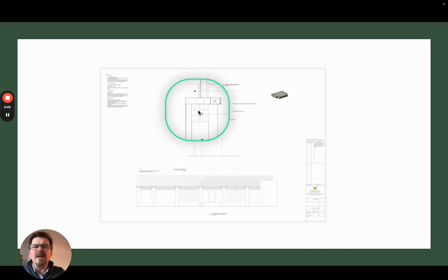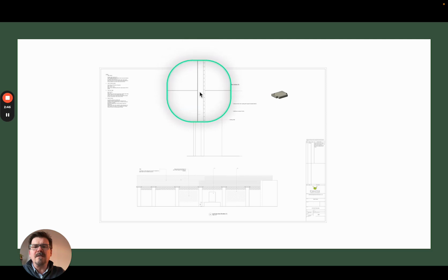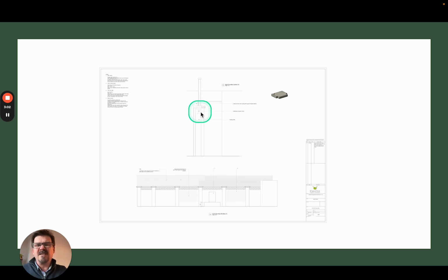So we've got the bricks, we've got 3 additional bricks going up here. We've got the posts and the fencing going up to the top there. So we're all thinking about the detail and the spacing. And we're also thinking about technicalities such as wind loading. So simply putting that post on top of the wall there isn't enough.